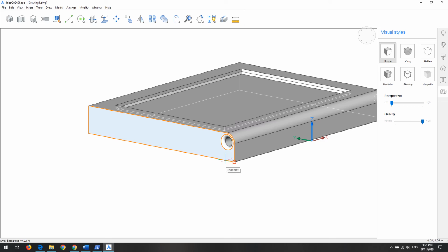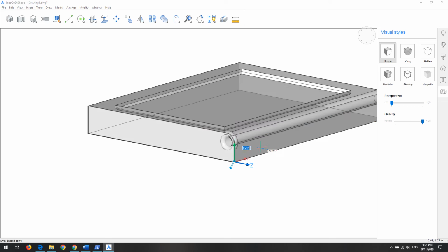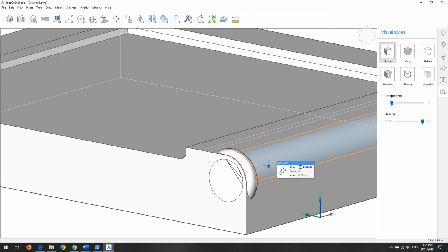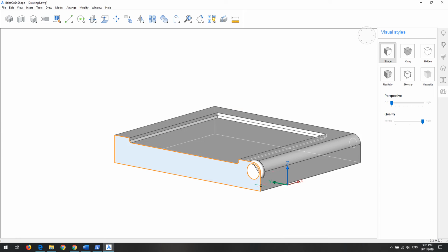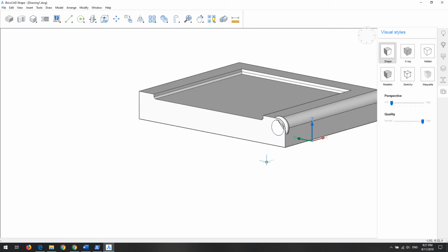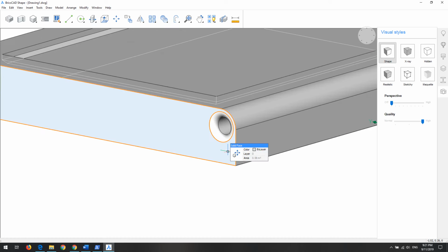Let's use this. Let's select the origin at this point, and you see we're moving the face, but it's not maintaining the geometry for some reason, because maybe it was not moving the fillet as well. Yeah, we didn't select the fillet, so we have to select this face.